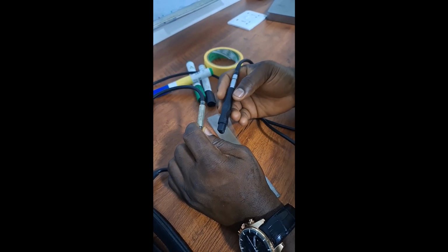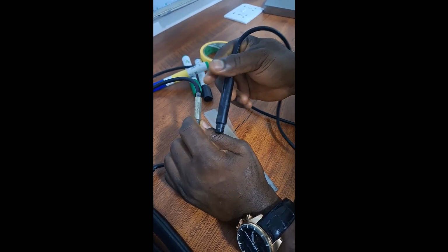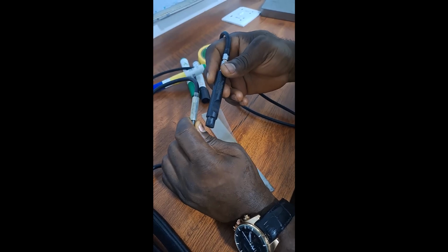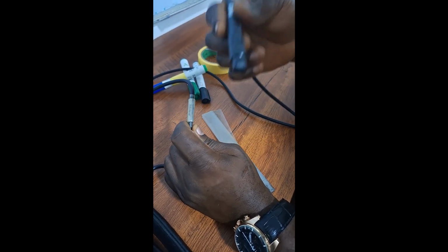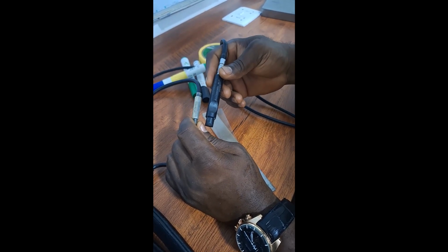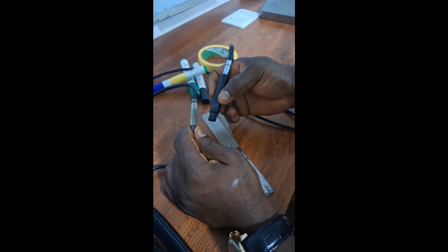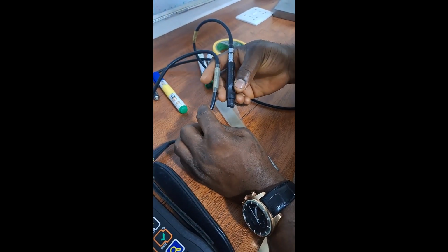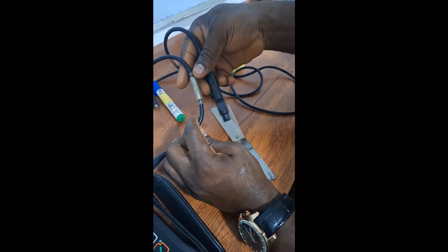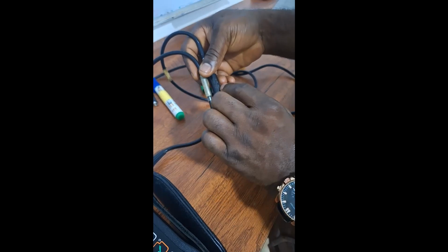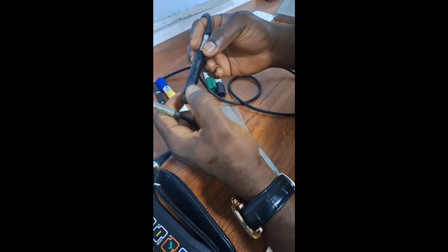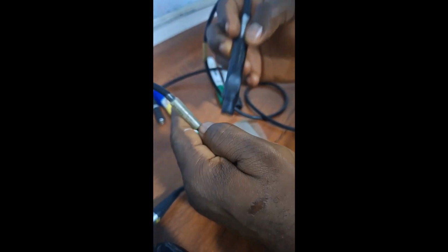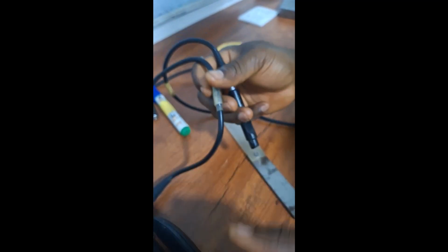So chances are this is going to give us issues during the test. Because they are not matching, your result may still come out, but at some point your indications will not be very clear. Your impedance curves may not be very clear, and it might give you issues. So you need to ensure that the probe matches the requisite cable. We cannot have a reflection cable with a bridge probe. So you need to correct that.